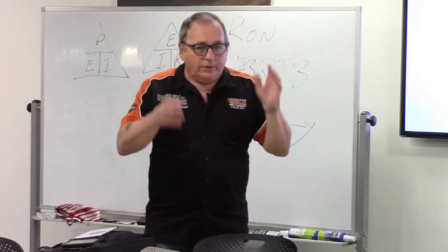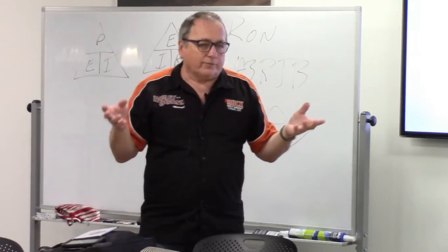Transformers are important because we use them for all kinds of things. We use them because we have 110 volts coming out of the wall, and we only need 13.8 volts for our radios. So we use a transformer to reduce that, and then we convert that AC to DC using diodes and whatever other fancy things we use. But the transformer is essential. Next, please.